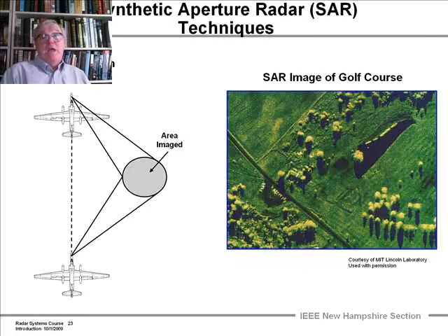Well, why do you use radar? Well, one reason is optical systems can't see through clouds. Okay? And with enough radar power, you can see great distances that would be hard to see through the atmosphere. But what are the impediments on building just an ordinary radar? Well, you can get very good range resolution. Notice this picture has very good range resolution and cross-range resolution. You know, they're about the same.